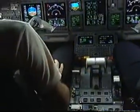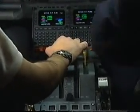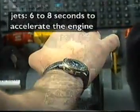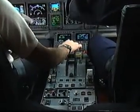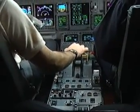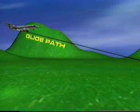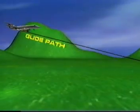Thrust demands departing from a normal approach thrust to full thrust can be achieved rapidly, but from idle thrust to full thrust, things are quite different and can take about 6 to 8 seconds. This value can differ from engine to engine, so the full 8 seconds is a reasonable value to keep in mind. This acceleration delay can be of intense importance, especially during approach and landing.